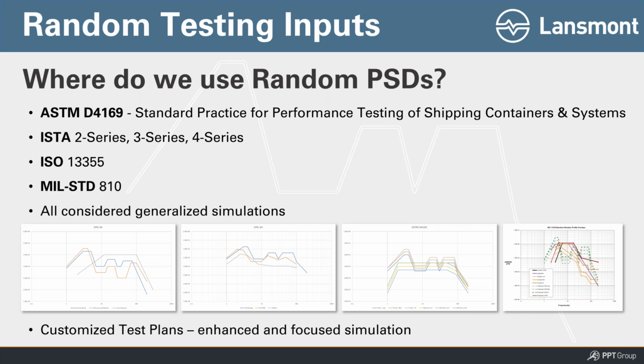You also can do customized test plans using PSDs, which is kind of what I just showed. Really, it's the ability to capture field data from various transport modes or various transport lanes, summarize that data, and use that to drive customized test plans. If some of the general ones don't work for you or don't work well enough for you, you always have the ability to go out and create your own. And there are methodologies for how you go about doing that.